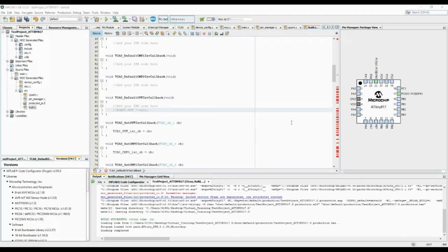So till now we have seen how to configure a project and generate MCU peripheral initialization code by using MCC. Also, we configured one pin as an input to read switch input and another pin as output to drive the LED. We also configured timer 0 to see the initialization method and its related interrupt service routine location, where we can add our customized code.